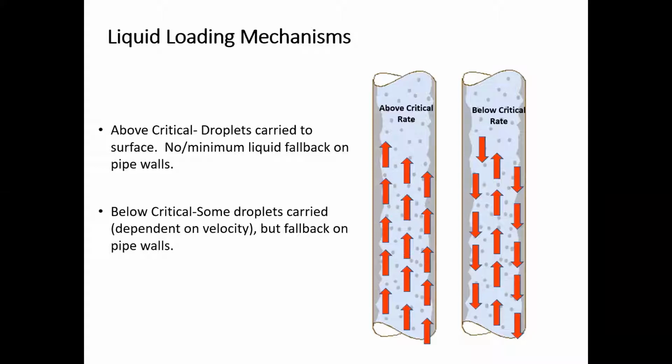Gas flow is beginning to head, slug, or transition from annular flow, which is an early sign of liquid loading. The well has either reached or is now producing at critical rate. Hydrostatic pressure from liquid load can prevent gas from traveling upward and exiting the wellhead. This is similar to the use of drilling fluid or salt water to kill a well and eliminate flow when drilling or working over a well.